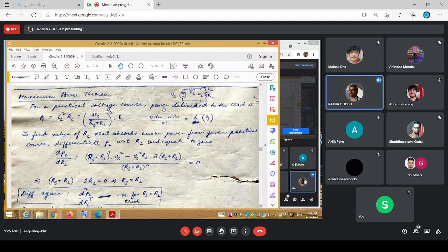By the way, superposition holds for voltages and currents. It does not hold for power or energy. Those are products: IL into VL, or integral dt. So superposition does not hold there, just as we saw that superposition does not hold for any dependent source, which is a multiplicative of two I's and V's or something. That same thing would apply.